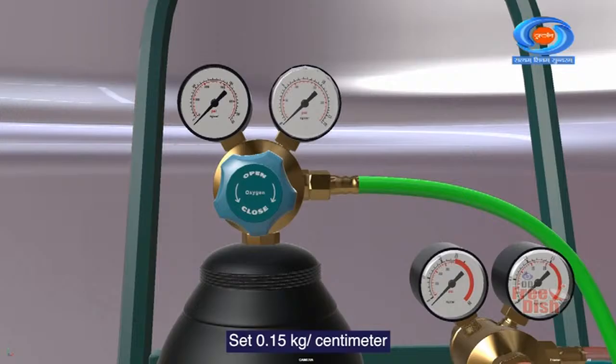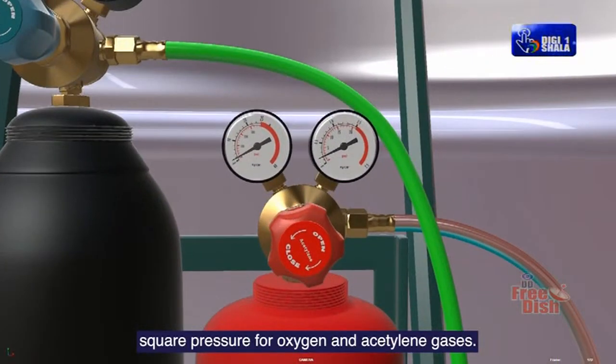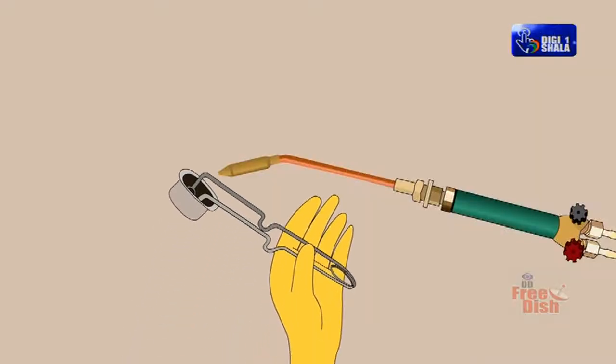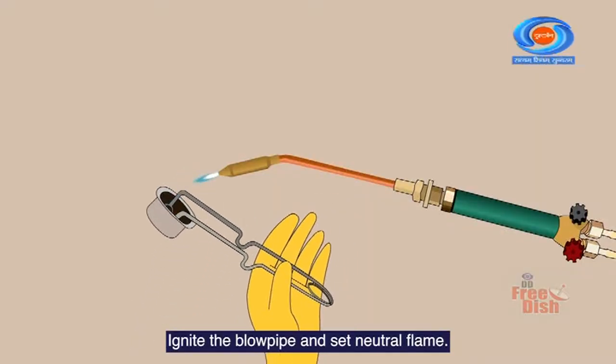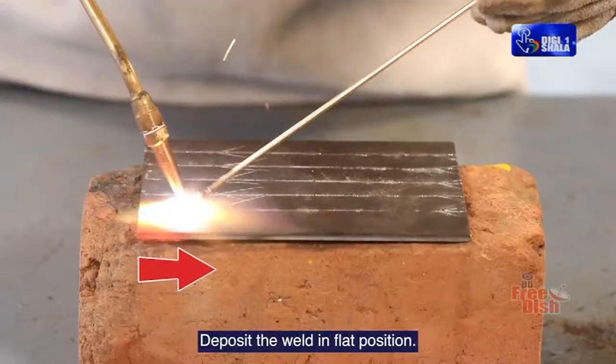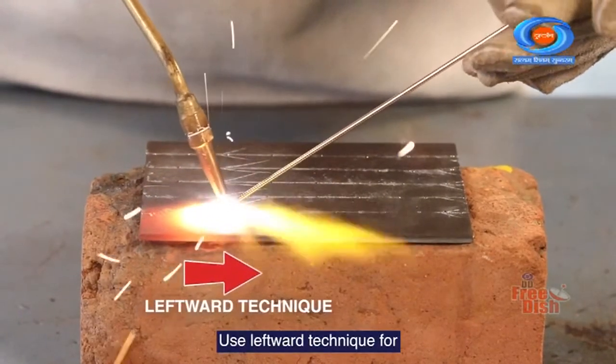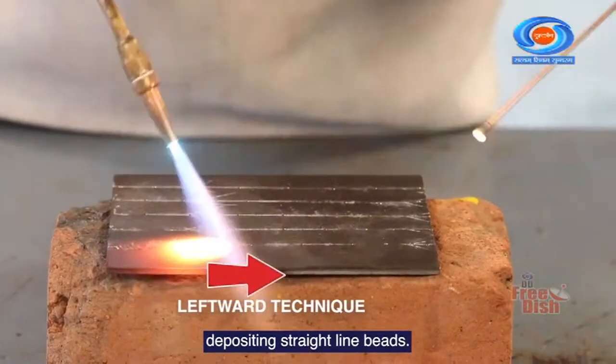Set 0.15 kg per centimeter square pressure for oxygen and acetylene gases. Ignite the blowpipe and set neutral flame. Deposit the weld in flat position. Use leftward technique for depositing straight line beads.